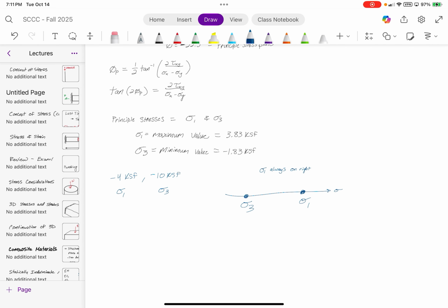But here's the thing. We know how they relate to each other here. So you could just use this relationship between the two to then solve for the equilibrium. And then that's how you get the value. How do I do that, though? Well, take the aluminum. Let's say we want to replace the aluminum with its equivalent amount of steel. So take that 250 and multiply both sides by it. So then the steel is just going to be 250 divided by 725. So it's just 10 over 29 PST is equal to PAL.